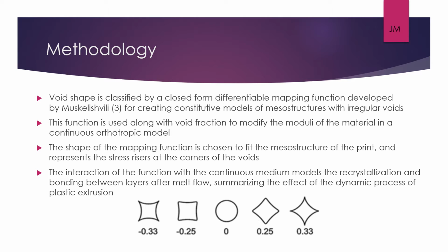And this interaction of the function is essentially acting as a model of the recrystallization and bonding between layers after a melt flow, and summarizes the effects of the dynamic processes of a plastic extrusion. And below you'll see a few different pictures which are demonstrating the physical representation of these void shapes and what those look like, which we will later compare with our results of our 3D printed material.